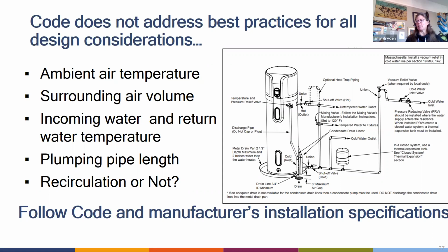The second one is the size of the tanks, as folks will be looking at the best size to make sure that they're providing the right service for hot water delivery. Unlike combustion gas water heaters, where you just crank it on and fire it up and you're accelerating that temperature pretty quickly, heat pump water heaters take longer recovery time.